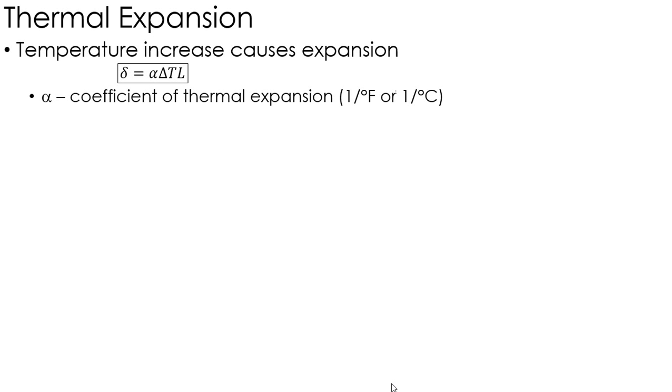We're going to talk about two things. The first being thermal expansion and the second being stress concentration. So with thermal expansion, it's really pretty straightforward. When the temperature increases, essentially we have expansion that occurs, right?